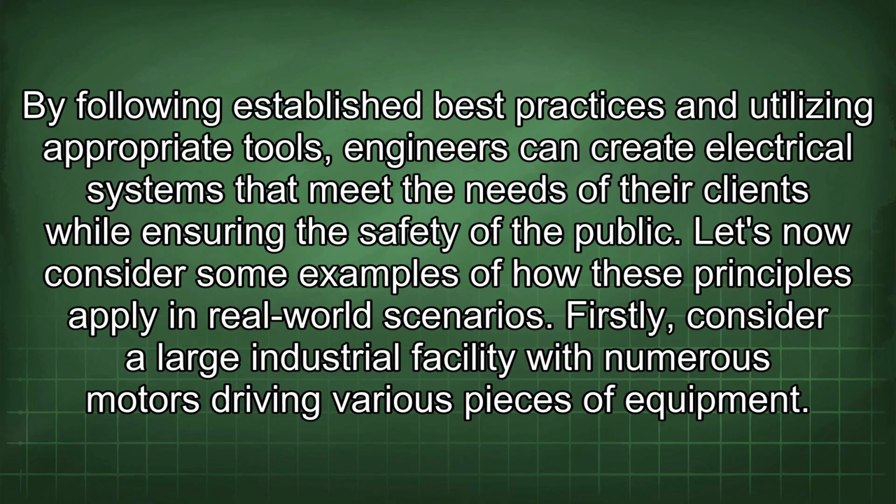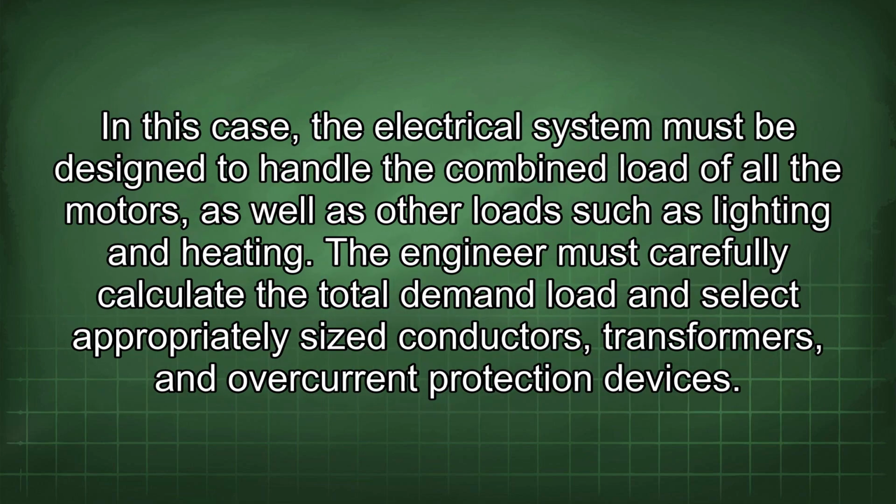Firstly, consider a large industrial facility with numerous motors driving various pieces of equipment. In this case, the electrical system must be designed to handle the combined load of all the motors, as well as other loads such as lighting and heating. The engineer must carefully calculate the total demand load and select appropriately sized conductors, transformers, and overcurrent protection devices.